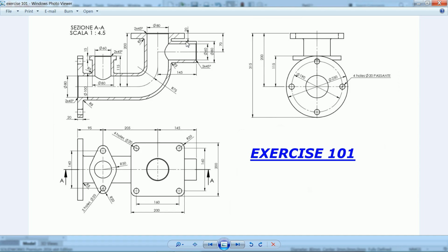Now there is one extruded part here and this is hollow, there are no joints. So this outer diameter 80, 60 inside diameter, thickness 10 millimeter, and distance from top edge is 70 millimeter. So we will create a plane 70 and 145 millimeter. Okay, so let's make it hollow.